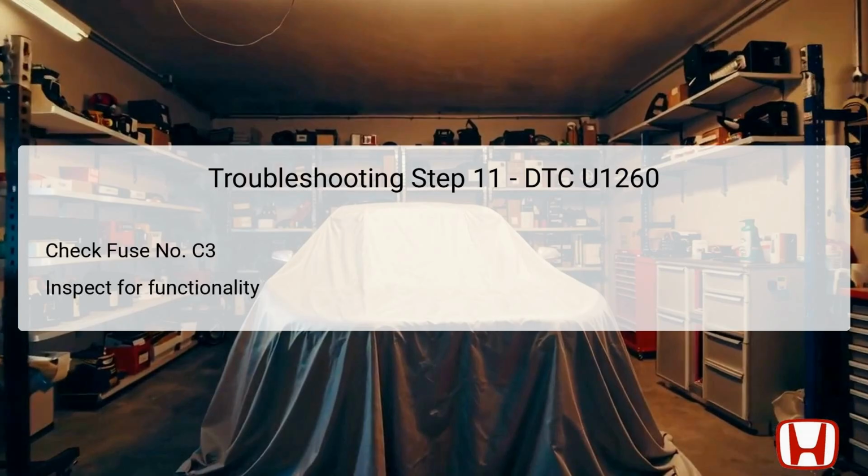repairs can be successful. The 12th troubleshooting step involves removing the auxiliary transmission fluid pump relay for examination. A relay acts as an intermediary, allowing low current circuits to control high current devices such as the auxiliary pump. After removal, conduct a test to assess the operational integrity of the relay to ensure it allows the necessary current to activate the pump. If the relay fails this test, it means it cannot effectively close the circuit when activated, leading to the U1260 DTC being generated.